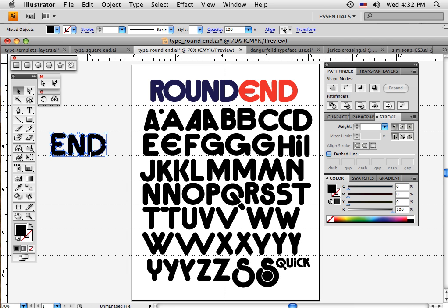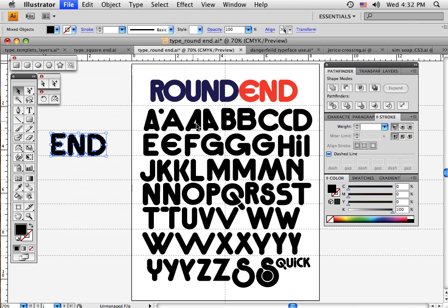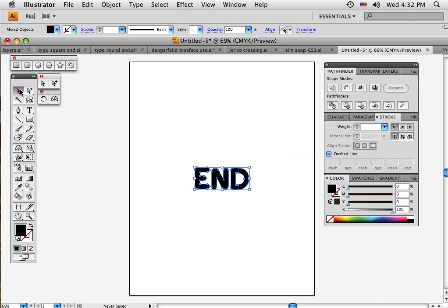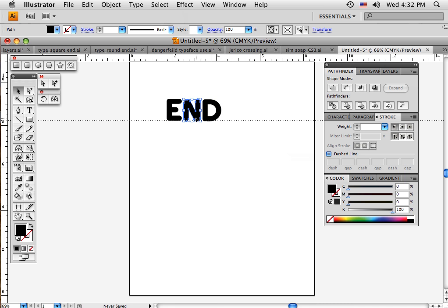Then you take these that you've selected and you go Command C, and you have them now temporarily on the clipboard of the computer. Open a new page, new, and when that new page opens, if you hit Command B, as in Victor, that puts those words there. Then bring in some Command R, bring in some guidelines, and start to build your word so that they're level on the guidelines. And check and see if it is level. Get a little closer. Go in with your magnifying tool and make sure you're right on the guidelines.